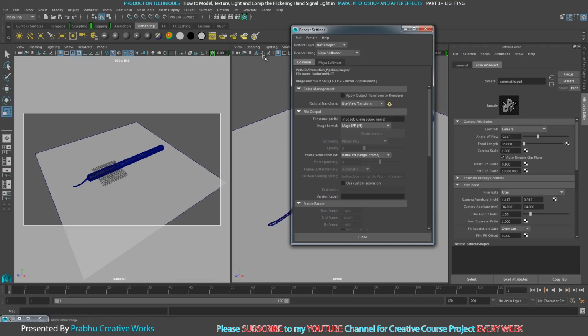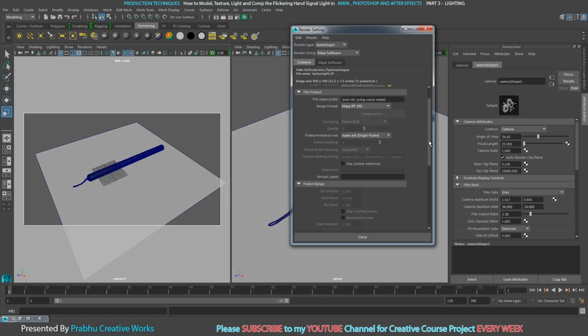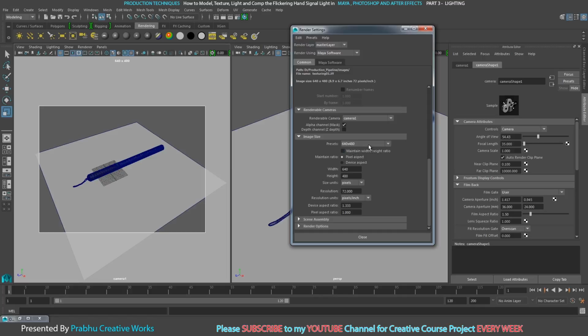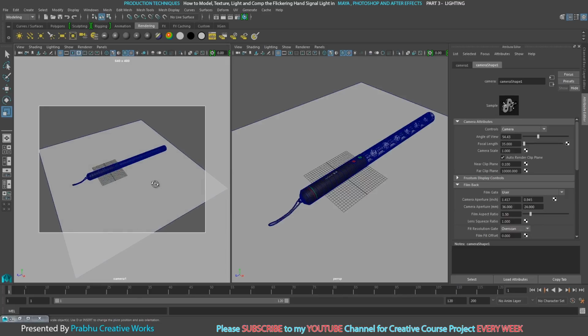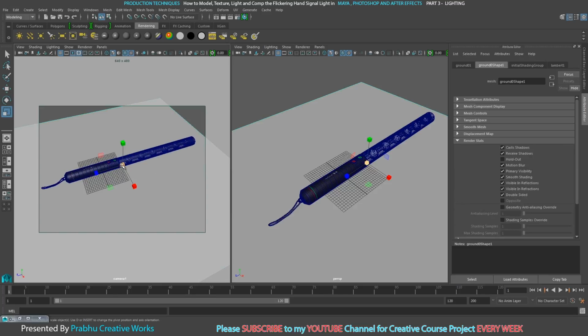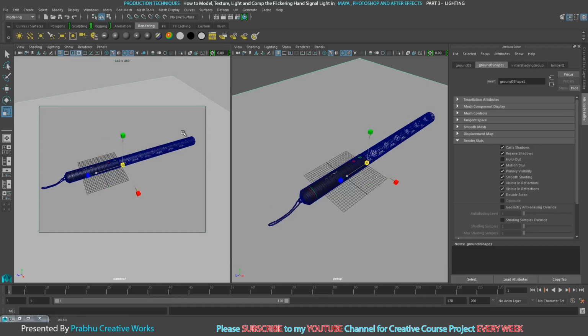So go to render settings, in the common tab, go down to the bottom. Here you have two options, renderable cameras. I want to choose my camera 1 because it's my renderable camera, and here you want to choose presets to 640 × 480. It's enough for when we start lighting. So press close. So I want to set my constant camera view over here and select the ground plane, and scale it much more. You cannot show the edge of our plane, so I will scale high.